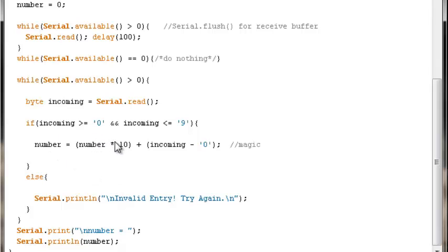So what happens? Say we're going back to that 15. The first pass through, we sent a 1. We put a 15 through the serial monitor. That means Serial.available is greater than 0. The 1 is read. The very first byte is read. It's pitched over here. It's in a character format, so it's really got the value of 49. But either way, it's a 1 character, so it'll pass the if test. Its integer value, or what you might want to think of as its integer value, is 49. 48 will be subtracted from it, which leaves 1 here.